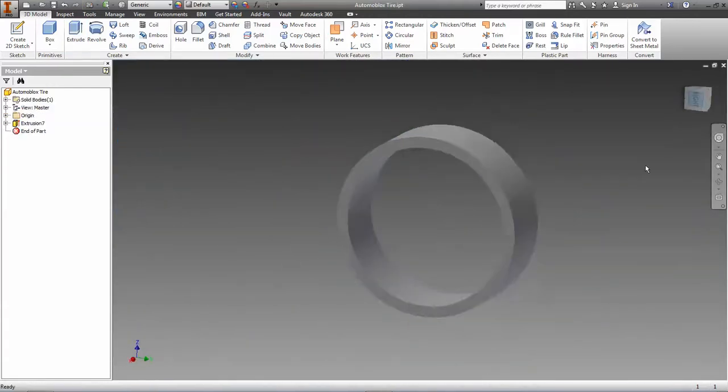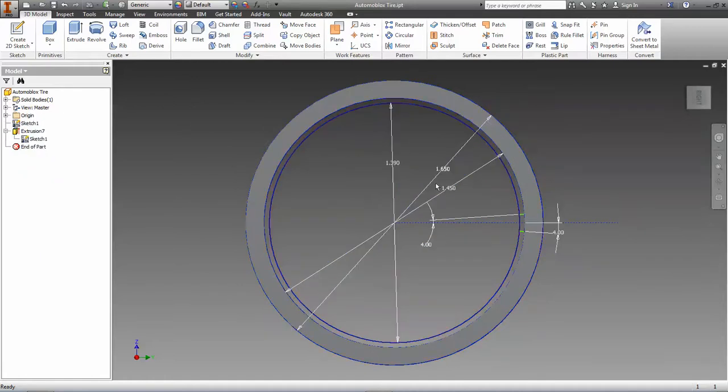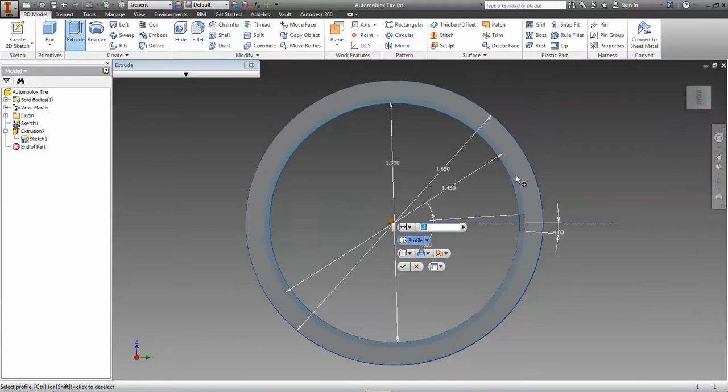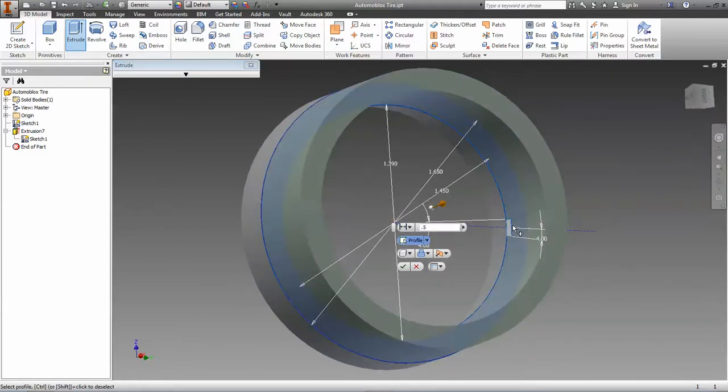Now, when we try and do our other extrusions, you'll notice the sketch is consumed. So we have to reveal the sketch, right click and say share the sketch. Now we can go and create our other geometry. There's a little rib that runs around the inside, and we need to pick not only that, but that extra little bit there. Oh, not that one. That one.